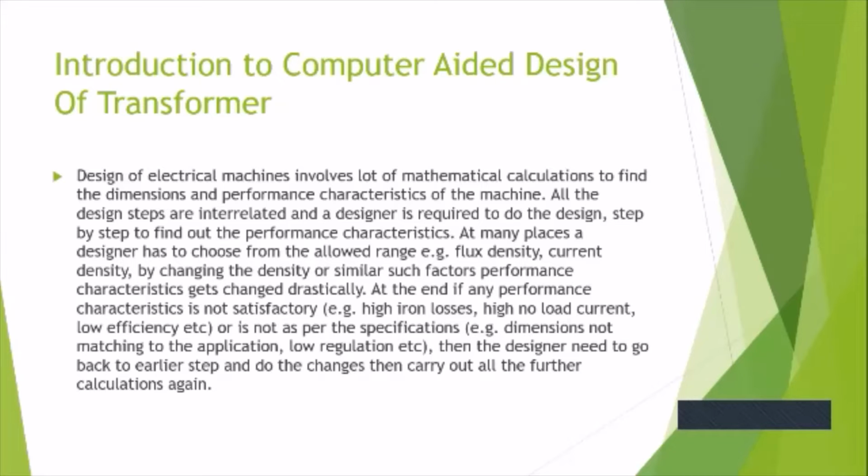At many places, a designer has to choose from the allowed range, for example flux density and current density. By changing the density or similar such factors, performance characteristics get changed drastically.